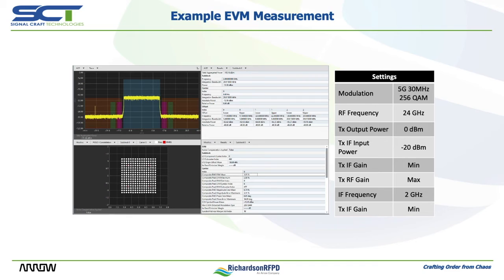For these tests, a 5G waveform is selected, which produces a 30 MHz 256 QAM signal. During our testing, we discovered that noise is being coupled onto our internal LOs. This noise is limiting EVM performance, and design enhancements are planned for the next hardware revision. In order to continue EVM performance evaluation, measurements on the following pages were made using external LOs.